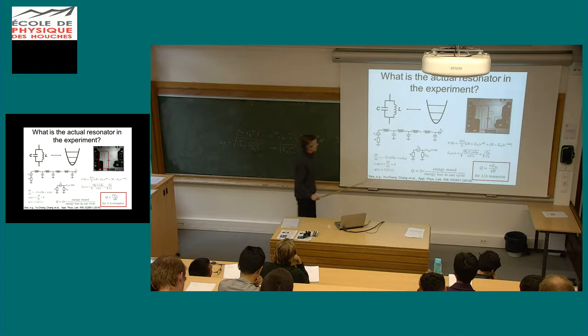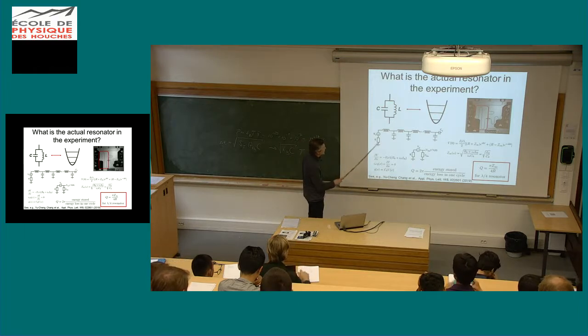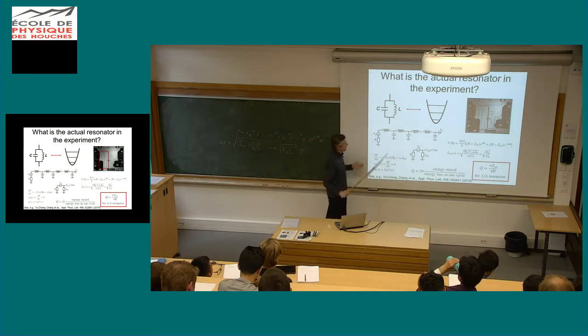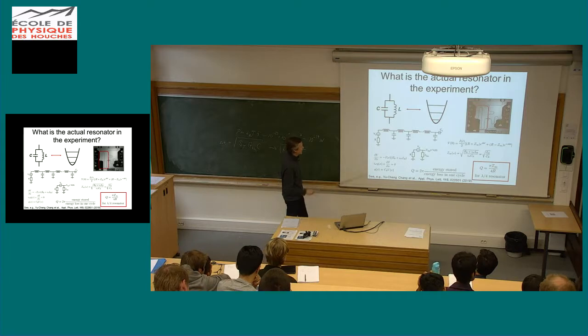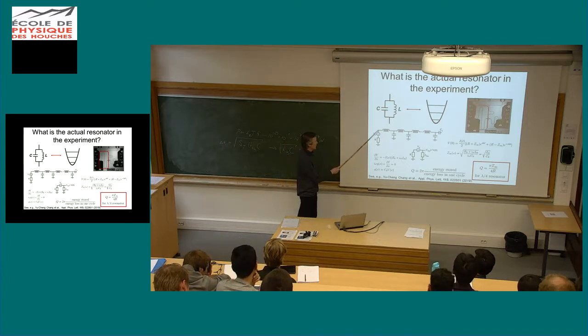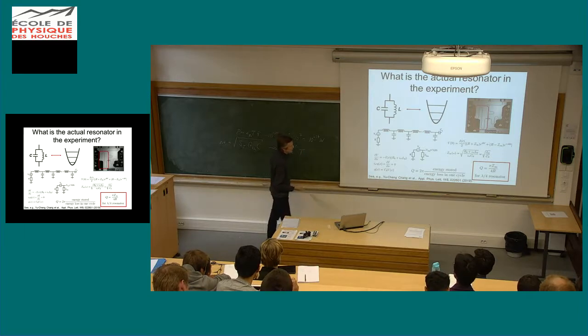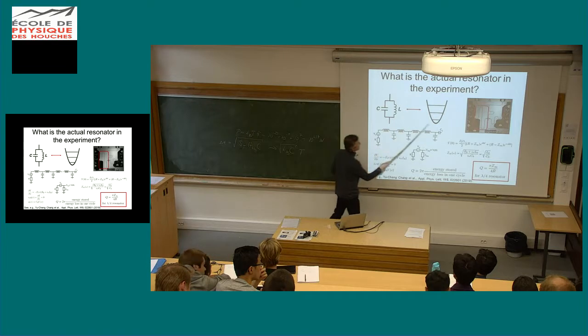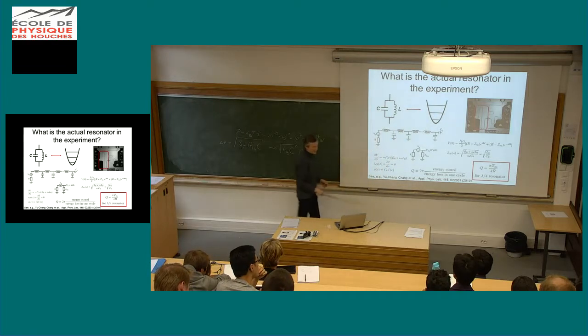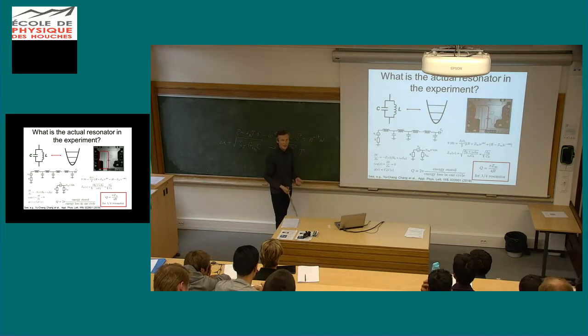So typically, if you just terminate this, you can choose the length depending on the frequency you operate at, and you talk about lambda/4 resonators or lambda/2 resonators. This just leads to either a current maximum or a voltage maximum at the end of the line. The particular thing that we do here is that for our experiments, we want to make this an open system. We want to make this a dissipative system because we are interested in thermodynamics.